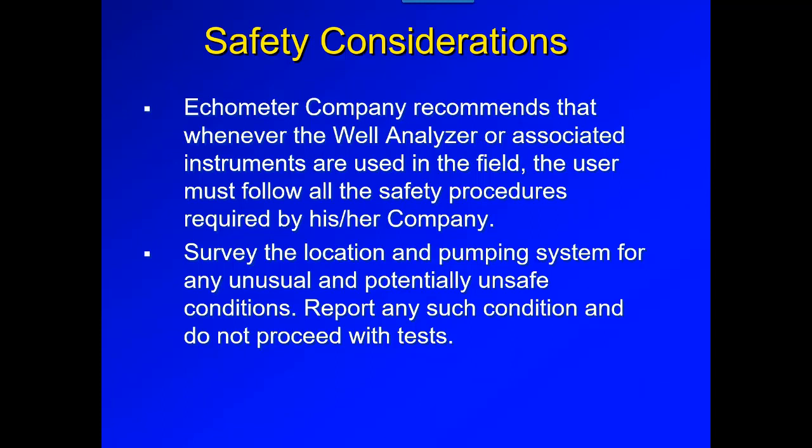Number 1, from a safety perspective, is we're going to survey the location and the pumping system to make sure there aren't any unusual or potentially unsafe conditions. If you have a wrist pin that is popping or a saddle bearing that is popping, and it's something that's new, it may be a time that you don't really want to be stacking out the well and put yourself in harm's way.